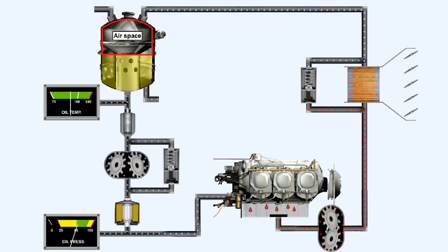Next, the expansion of the oil, and therefore its greater volume as the oil absorbs heat from the bearings, necessitates a greater volume of space than otherwise would be the case if the oil was cold. Likewise, the oil suffers quite a beating from the engine components, as they attempt to thrash air into it in a similar manner to the preparation of a soufflé. This aeration causes the oil to froth, which greatly increases its volume. Another reason why the airspace is necessary is the fact that oil can be displaced from the variable pitch propeller and any other automatic controlling devices when they're used.